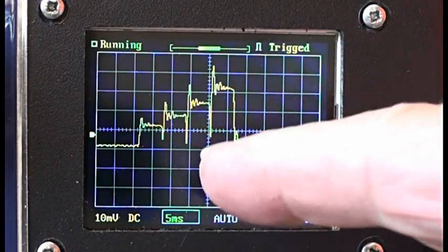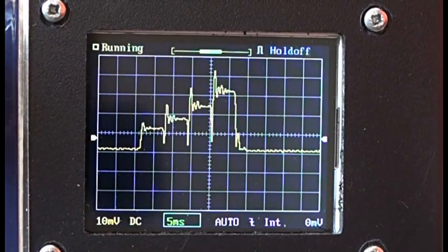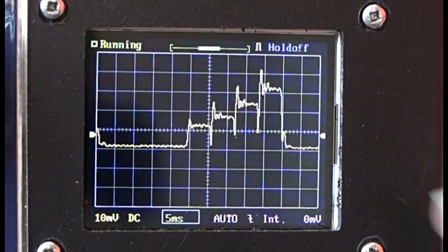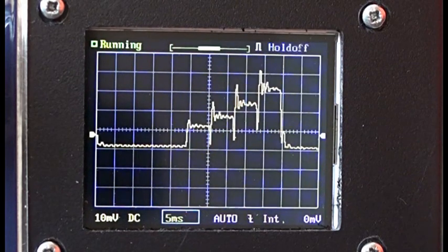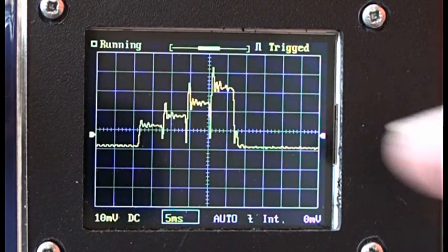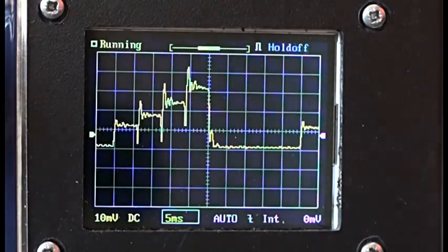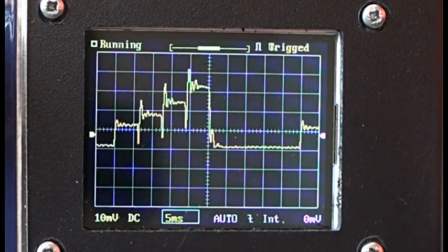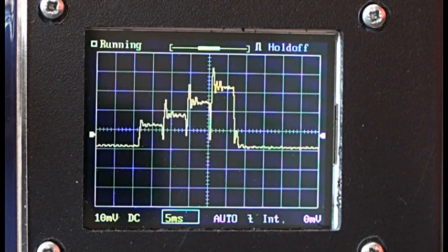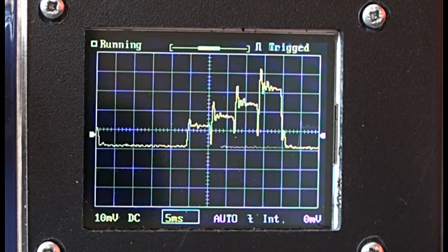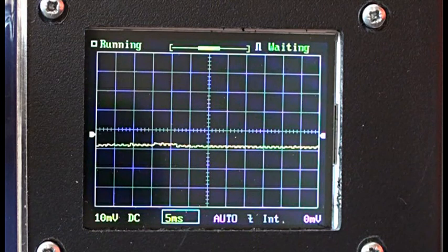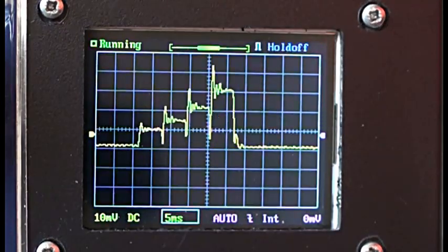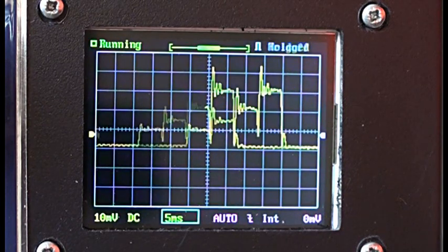There's the stair step waveform coming out of the RF detector, going through the linear. You can see it's pretty good. A little bit of an overshoot, but that'll be somewhere in this circuit. Drop the gain, drop the signal down now. So this is what it sounds like when you tune it.